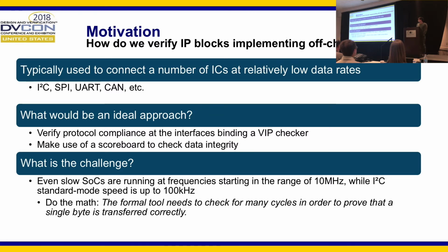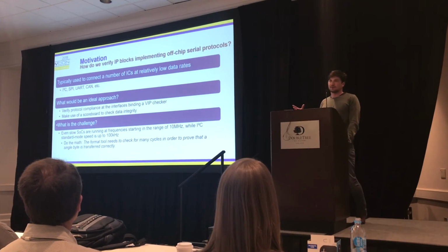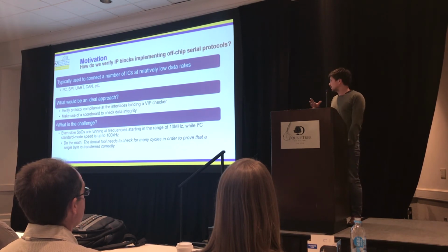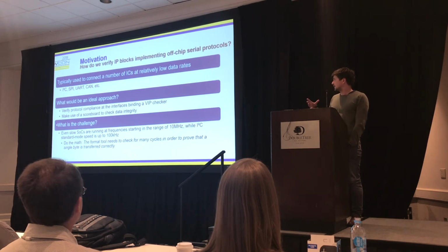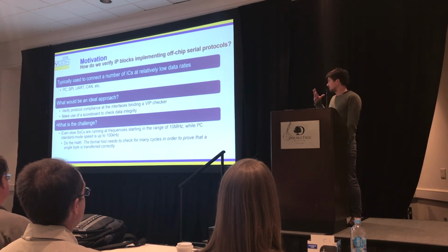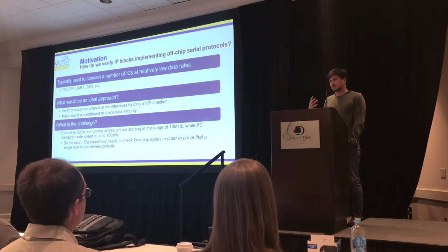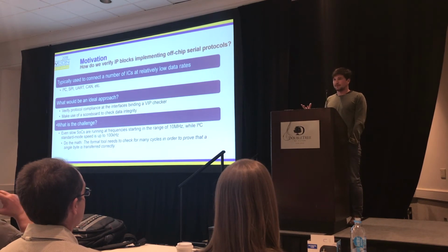Because even slow SoCs today are running at higher clock frequencies, and the standard mode in I2C is up to 100 kilohertz. So if you do the math, the formal tool needs to check many cycles in order to prove that a single byte is transferred correctly. What would be an ideal approach to verify such an I2C design or serial protocol? First of all, you have to verify that it's protocol compliant, and after that you have to verify that the data doesn't get corrupted or there is no data loss.